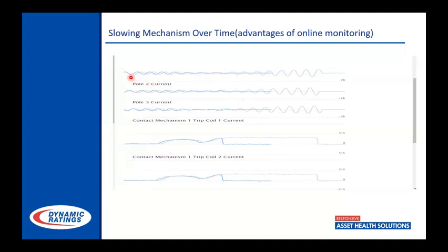But we can see that this current was, I want to say, around 400 or 500 amps we were running in normal. But we can see that this breaker starts to open, and this current drops to almost zero. So it was dropping very low, around 50 amps, I think, during the initial part of this failure. But then we see that the current is ramping back up at the end of the operation. So now we have to start asking, well, what would cause that type of signature?